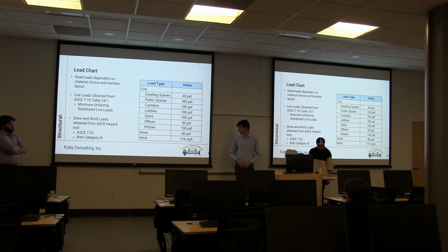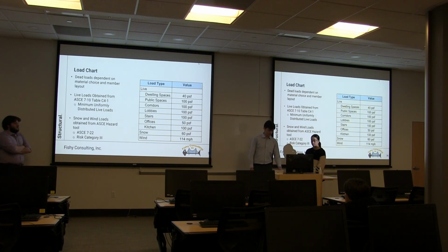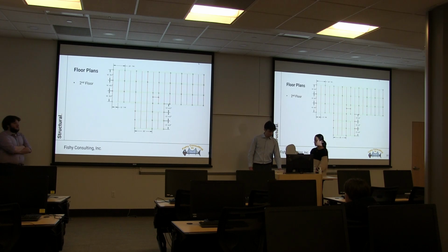So I think that this 7-22 uses a couple different factors differently than 7-16 to come to 60 PSF, so I might be reevaluating and making an educated decision on a different load to use, and use 7-16 standards to design too. We are in risk category 3 because people are always going to be in the building. There will be medical staff and just an at-risk population in there already.